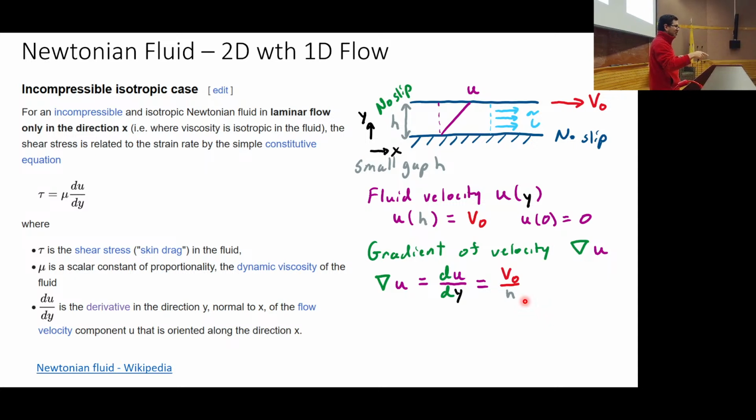Oh, come on. No. Where are we measuring the force? One of the surfaces. In which direction? Parallel to. So what do you do? You take a little force gauge, or you can make this a vertical setup, whatever you want to do, and you measure how much force you have to pull that top plate with relative to the bottom plate.